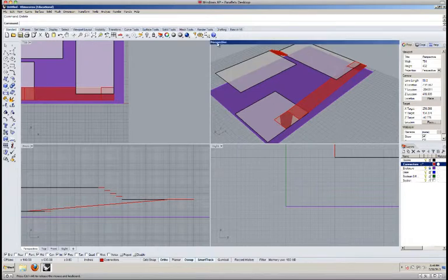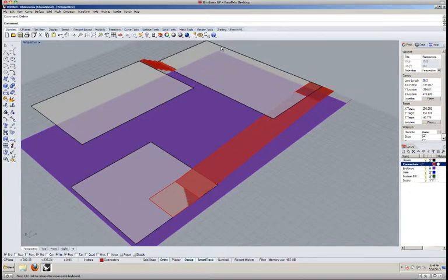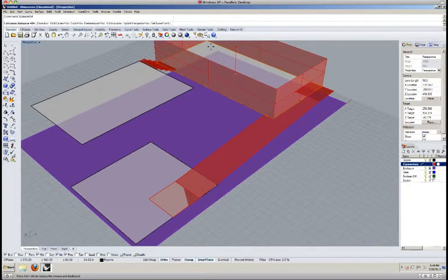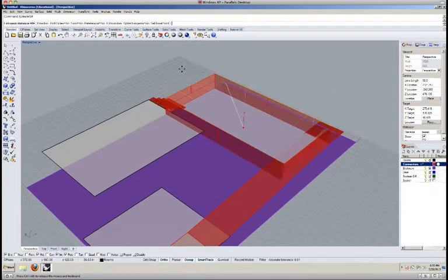Okay. The next thing we want to do is start to think about, well, we've really kind of set the openings between the rooms, but we need to turn those planes into volumes. So we know that each of the 3 rooms is 12 feet high, so I'm going to take each of these, extrude surface, EXTRUDES, and this time we want it to extrude perpendicular to the base plane, so we can leave it as the default.